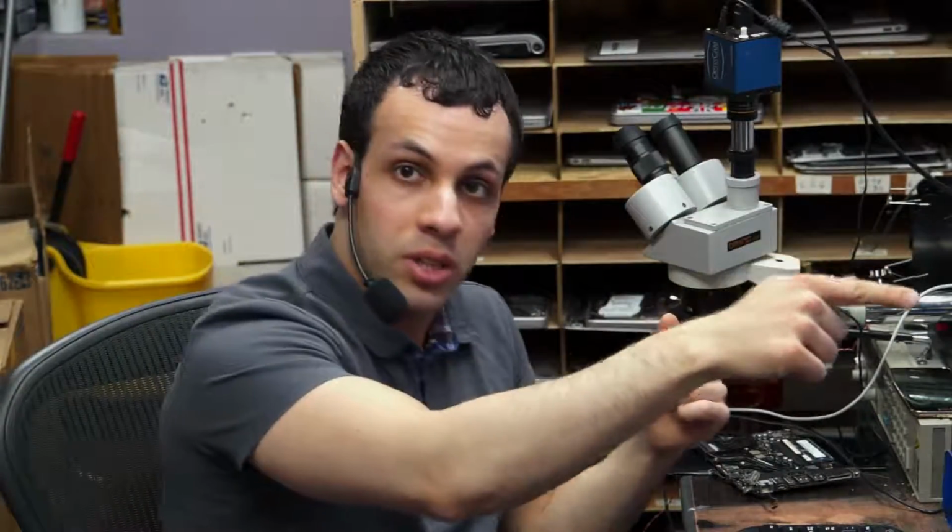So that means that if 12.6 volts doesn't exist, I can stop troubleshooting the 5-volt circuit because the 5-volt circuit, even if it worked fine, will never create anything because my 12-volt circuit doesn't work. This is the importance of being able to troubleshoot power rails, of knowing and understanding how they work and where they are in a schematic so that you know what to look for, so that you know what to troubleshoot, and so that you're chasing the right rabbit.